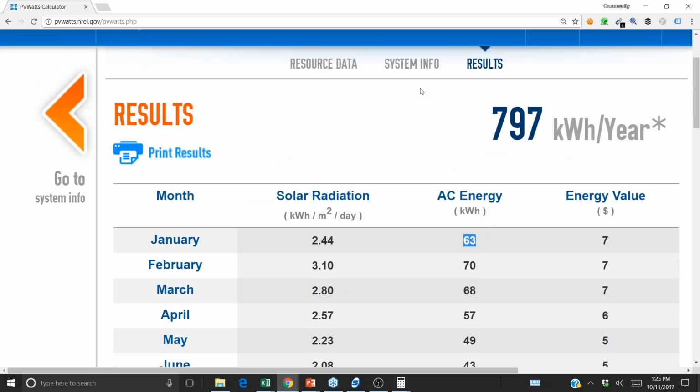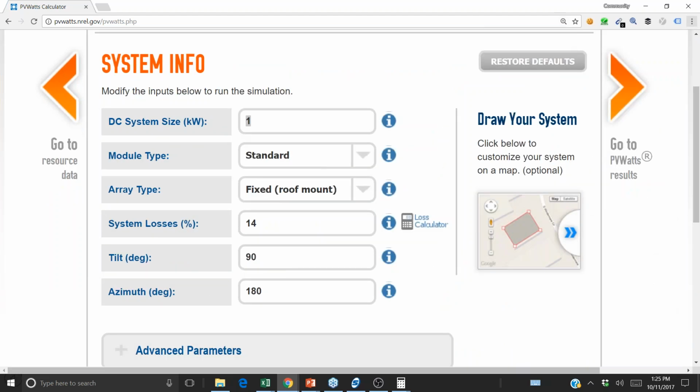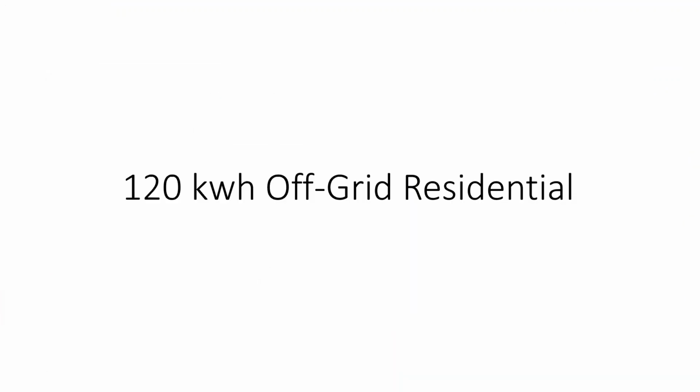It would be better to have a rectangular building where you have a flat array for summertime production and a perpendicular array for wintertime production, rather than having an array at a 30-degree tilt optimized for annual production. So your design can get a little bit more site specific, but again, the differences between most array tilts and orientations are only going to vary by about 20%. So it's not something I would lose too much sleep over. We're still in a situation where you're kind of conforming the array to the rooftop rather than the other way around.